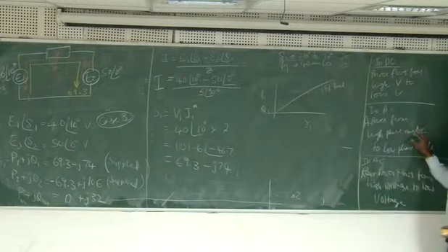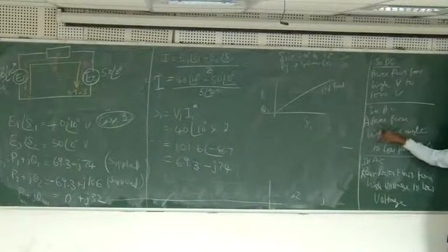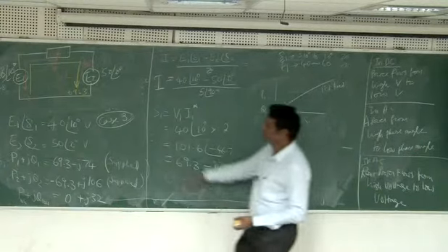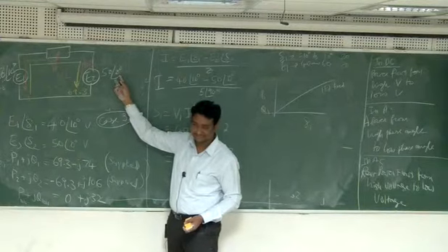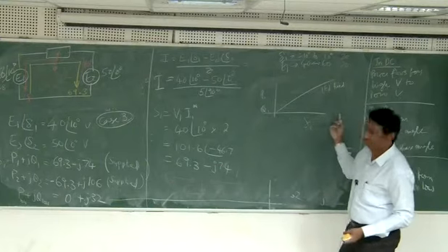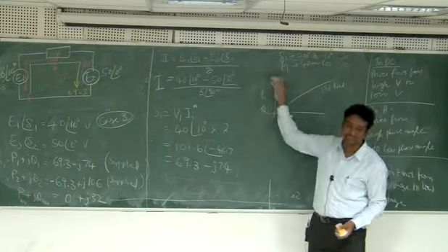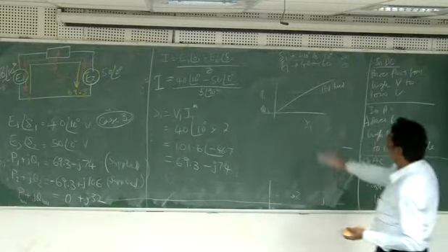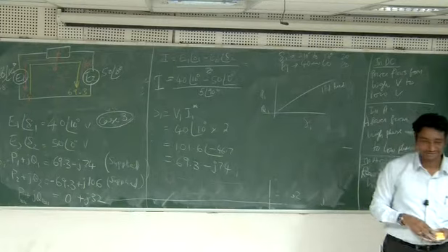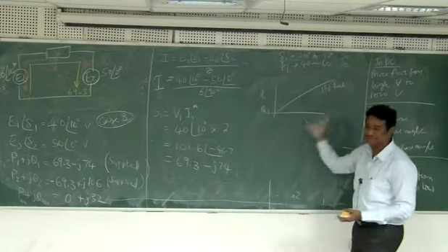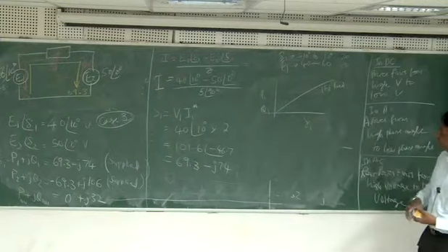See what we have written here. In an AC circuit, active power flows from high phase angle to low phase angle. Okay. So this is fixed. Delta 2 is fixed at 0 degrees. So delta 1 keeps on increasing, maybe -10 to +10. Will P1 keep on increasing? That is a question. And will it be like a straight line? So you can try that. You can try this combination and then find out how it is.